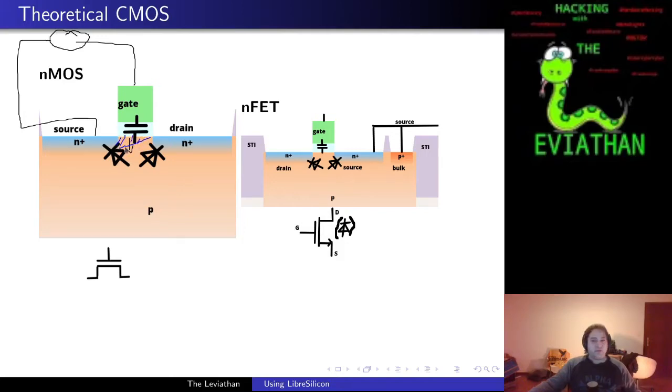First, the recombination leads just to the change from p-doped to neutral silicon, and the higher the voltage becomes, the further you overcome the required bandgap energy to turn the p-doped silicon into virtual n-doped silicon, and that creates here a channel between the two n-doped zones, which is also virtually, temporarily n-doped. That's why NMOS and NFET are also known as n-channel transistors.